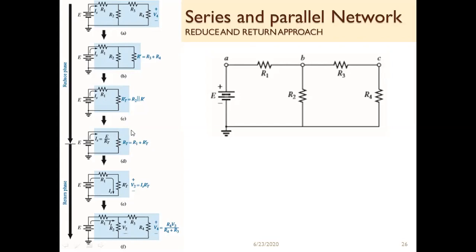So if we made it one over here, then now it is the simplest circuit where there is one voltage source and one resistor with it. So simply for determining the current, that is the source current IS, we will apply Ohm's law. I is equal to V divided by R. Here instead of V there is E, and instead of R there is RT. So I is equal to E divided by RT, which is the source current over here. So we can find current over here if we already found the total resistance.